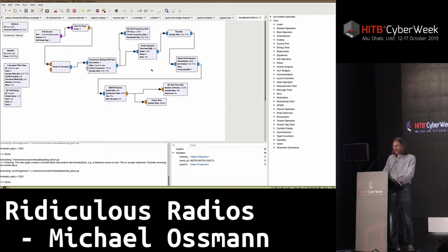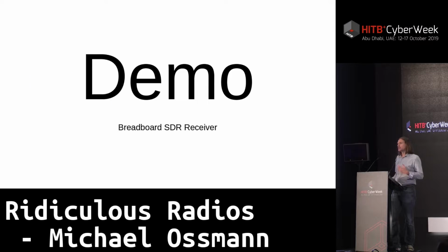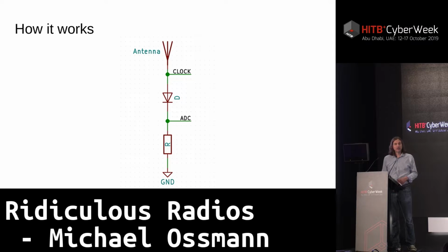Now, one drawback of this approach is that I had to use a fairly high-powered transmitter. And the reason I had to use a fairly high-powered transmitter is because there's no amplifier in this receive circuit. It's the crudest possible circuit I've been able to devise, the fewest components. And that means it has some drawbacks, but it is functional. As long as the radio signal is strong enough, this simple circuit that can be built out of components that you might find in any electronic device